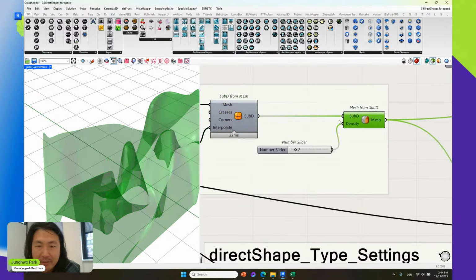And this mesh subdivision, we can also convert it again as a mesh, and then you can change the density of the mesh. For some reason I don't show the mesh edges, but here I just enabled it, and you can see here we have a much denser mesh, which looks like a paper model. But creating this kind of thing as a Revit family is tedious. But direct shape, in this case, if I shoot, and I'm just going to highlight this in my Revit viewport,